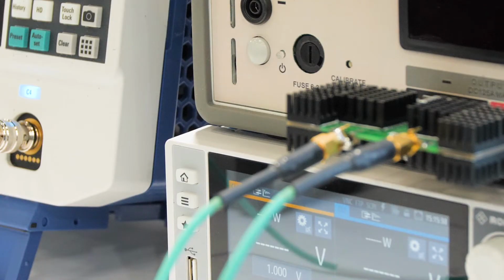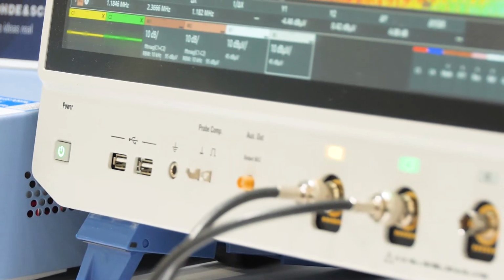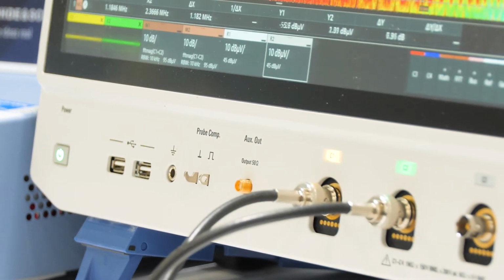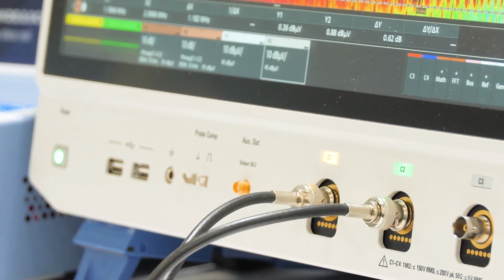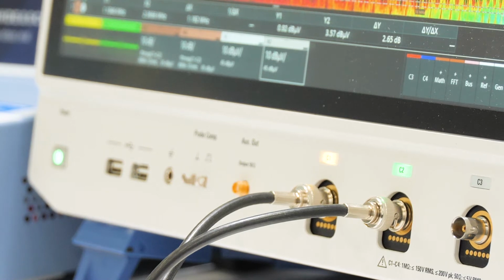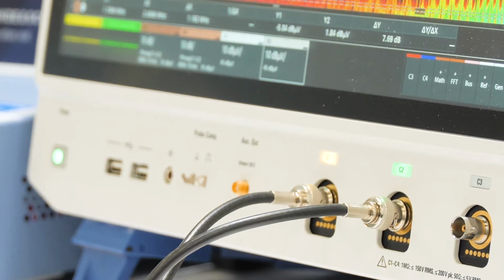The problem we're trying to solve is measurement of differential mode and common mode interference, conducted emissions in this case. Typically with EMI measurement equipment like receivers, you have one channel and can measure one spectrum. But when you're looking at differential, you either have to separate the common mode and differential waveforms, or monitor both sides of the power separately, so you can measure the plus and minus wire. The nice thing about this oscilloscope is a really powerful spectrum analysis feature that allows us to set the resolution bandwidth, span, and center frequency independently of the oscilloscope settings.